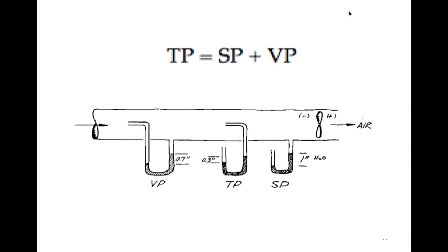So just like that, whenever we see a lower pressure than an adjoining area, we know air is going to move in that direction, especially when we're working with ducts. Now, in a duct, there's two kinds of pressures that we're concerned with. One of them is static pressure. And static pressure is the pressure that is present all the time, acts in all directions.